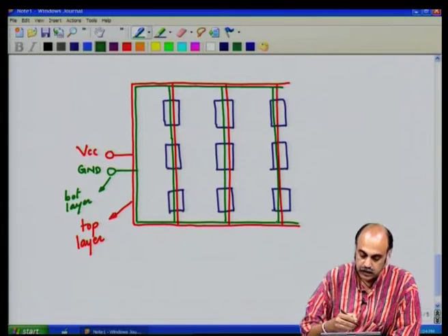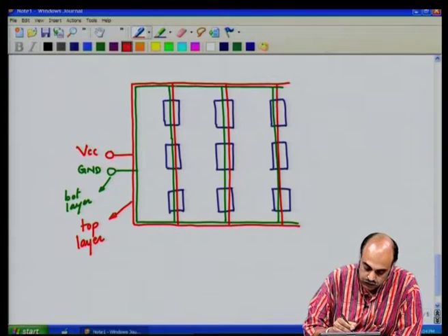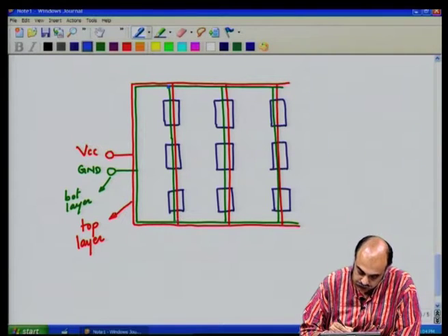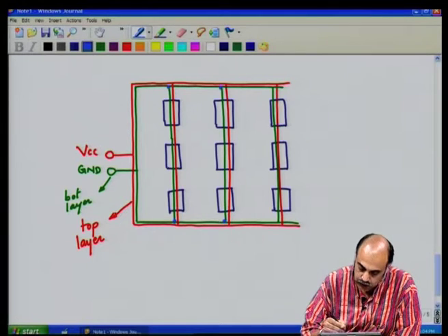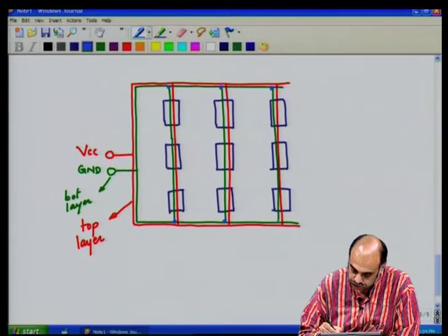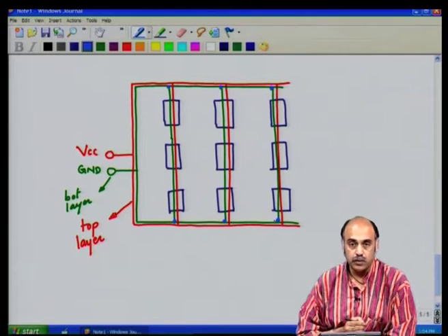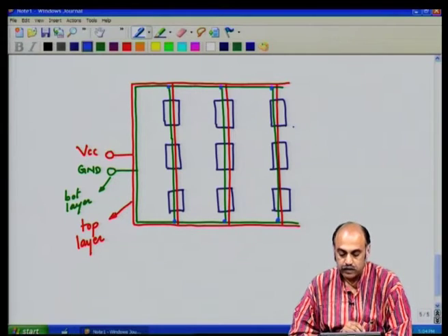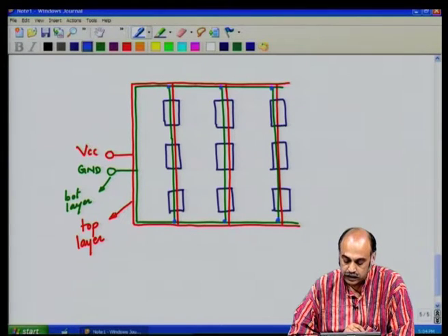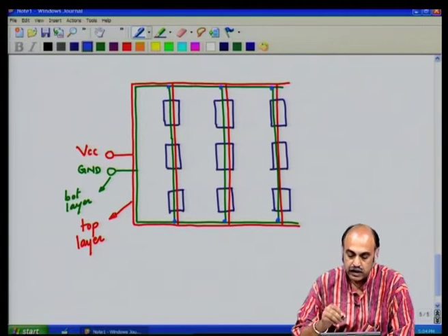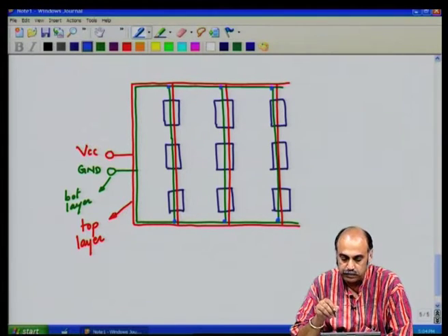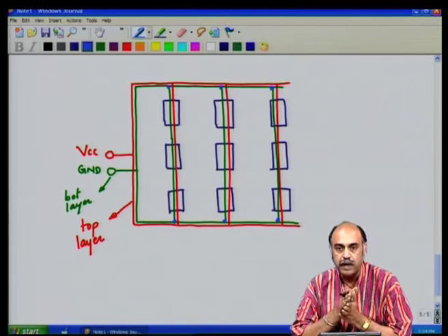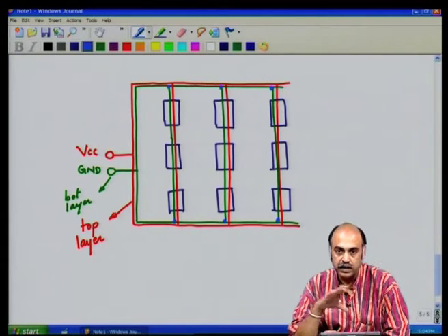You could directly connect them as such, or you could connect them and then pass it through a PTH, plated through hole. This is also okay, this is also fine. You could do that either for the ground or for the supply. So, this way you have again connection to all the ground and supply connection to all the components, and notice that the ground and supply lines are going together parallel. So, that you are maintaining a